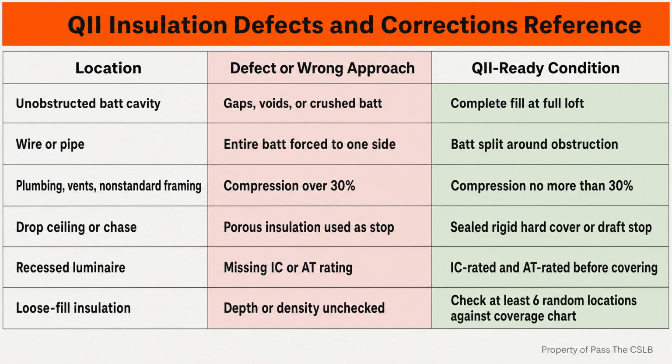For above-grade wood-framed walls separating conditioned from unconditioned space, the 2025 California Energy Code source identifies an assembly U factor of 0.095 for 2 by 4 framing, commonly achieved prescriptively with R15 cavity insulation. For 2 by 6 framing, it identifies an assembly U factor of 0.069, commonly associated with R21 cavity insulation. I treat those as compliance document checkpoints, not permission to swap materials by memory. The approved project documents and current requirements control the actual build.